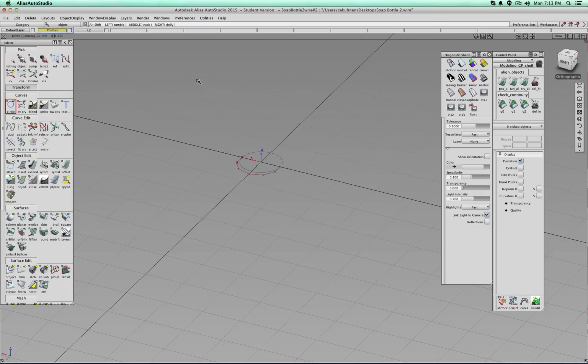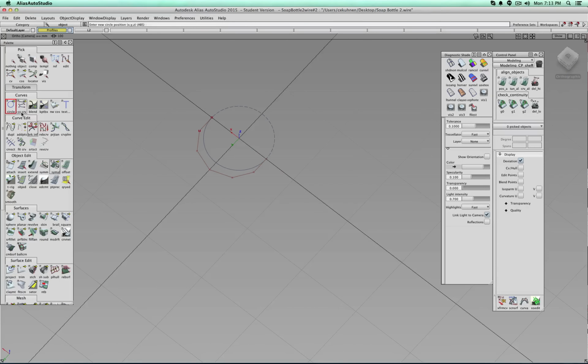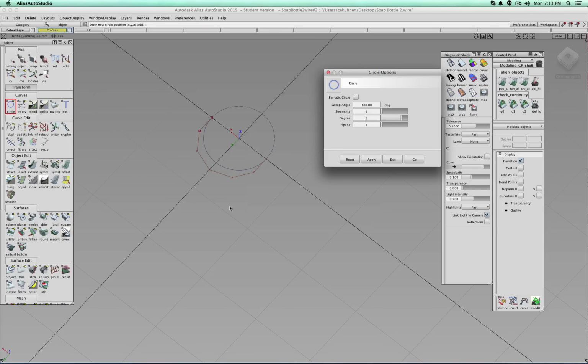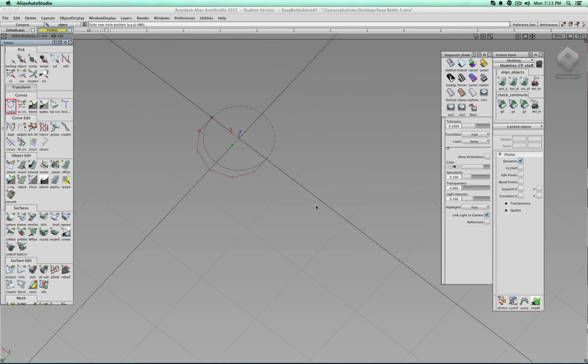There, wrong layer. So the main reason why, for example, I selected this half circle, you see how the CVs are positioned. The first two and the last two are perpendicular to the mirror axis, so I actually get perfect G1 tangency along there.